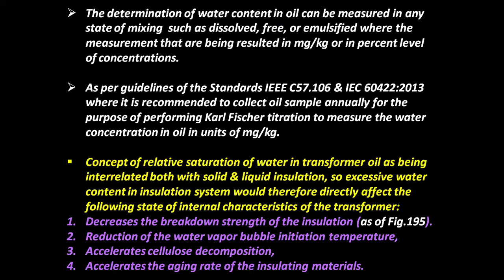As per the guidelines of the standards IEEE C57.106 and IEC 60422:2013, it is recommended to collect an oil sample annually for performing Karl Fischer titration to measure the water concentration in oil in units of milligram per kg.